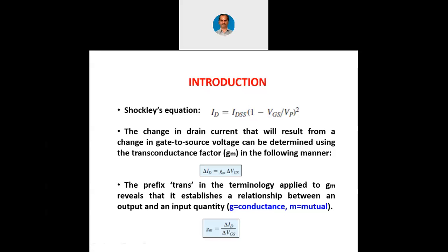But in a JFET there is no beta at all now, right? We want an AC quantity now. So gm has to be delta ID by delta VGS only, around the Q point. It is not a DC quantity, so we cannot directly write it as ID by VGS, because in the transfer curve the slope keeps changing. You can already visualize the transfer curve. The slope keeps changing at every instant. That is when we have to find gm at a particular point in the transfer curve, and we have to specifically define it as delta ID by delta VGS.